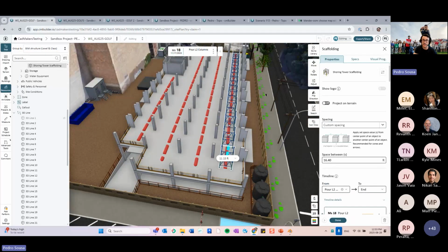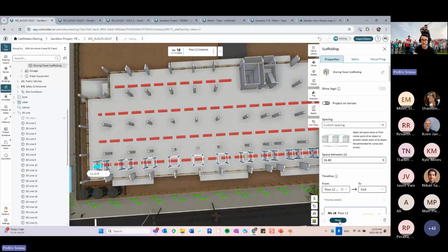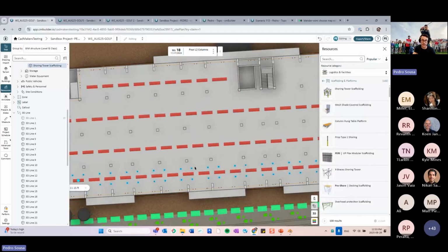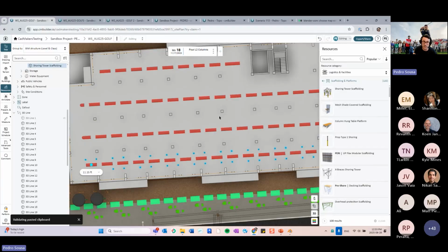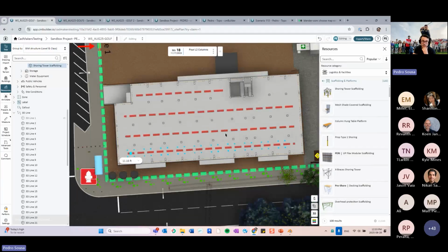So you can copy paste this element to the side, right? So when I do a Control C, Control V over here, it's going to take some time for the preview to show up in my view, but the copy paste will show up wherever my mouse is. So if I don't really care about the accuracy and I just want to show where they are, I don't need to create these templates. I can simply create a line and then copy paste and bring them over.